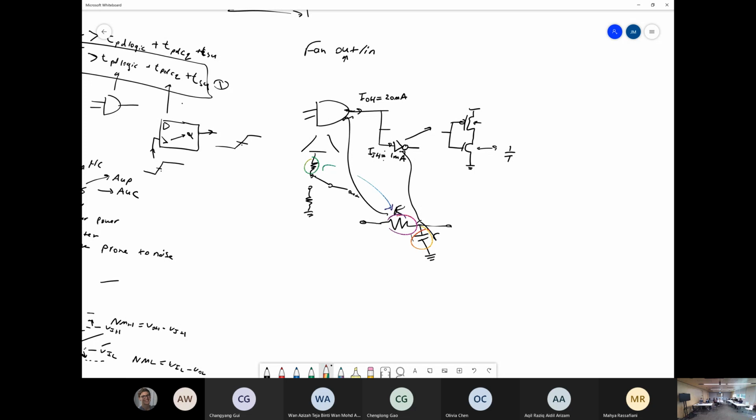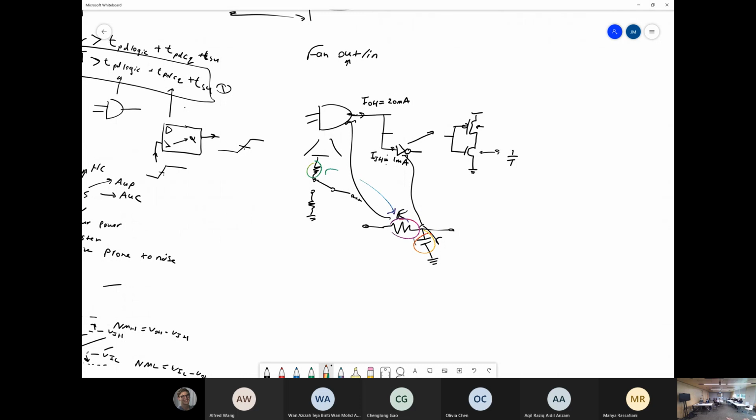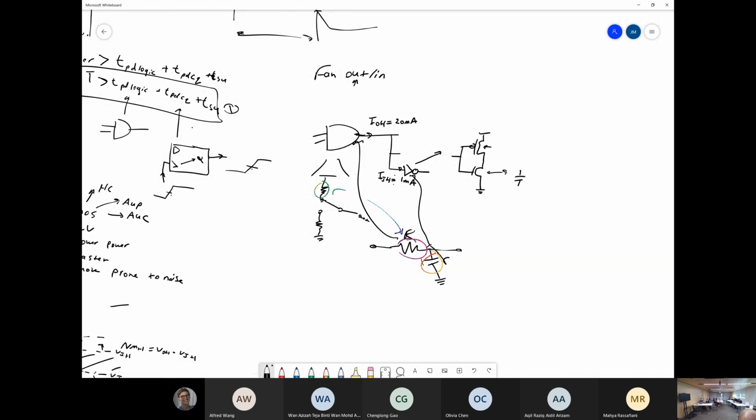We need to run the ADC data bus at like 100 kilohertz, right? Calculate the value of the pull-up resistors. You'll have to go in, look at the data sheet, find the equivalent input capacitance values, find the speed you want to run it at, which is typically given, and then you'll calculate R. A useful thing to note is that your propagation delay,